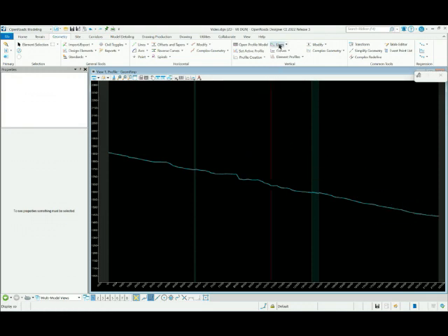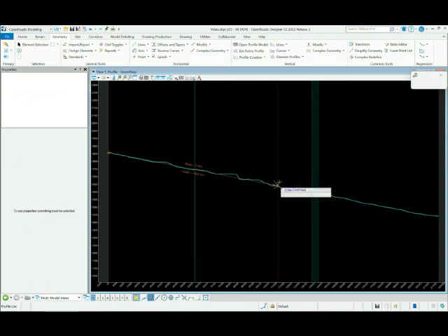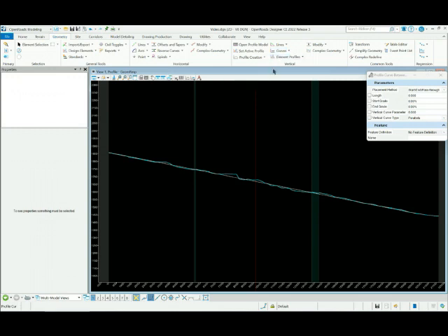And from here, you're just going to click on from the vertical tab on lines, and you'll be able to get the slope that you want in order to minimize the cut and fill. And then from here, you'll be able to make your sags and crests from the vertical curves by entering the slopes that you have right here, and then it will create the parameter needed.